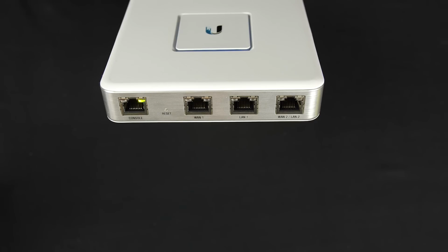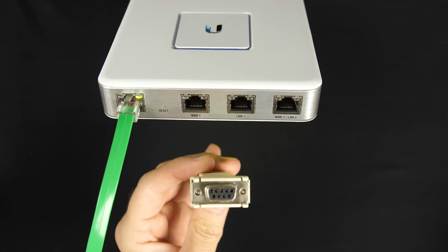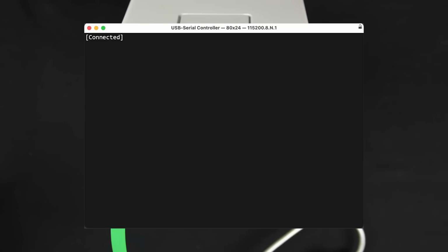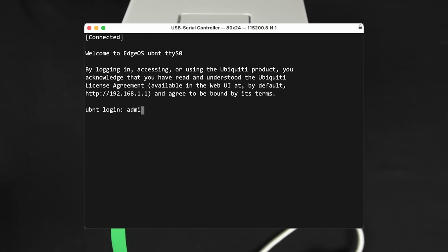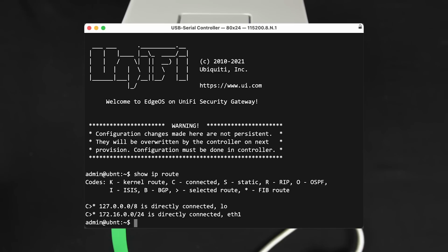But there still tend to be niche devices that use this serial interface, like this router that has a console port. This is actually a serial interface, and with the right adapter, we can connect this to a computer and use a serial terminal program to log in, configure, and troubleshoot this router using a basic text interface. And that's what I want to add to my breadboard computer, a serial connection that I can use to create a basic text interface like this.